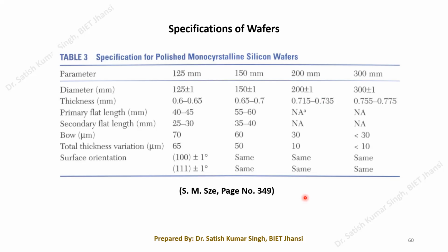So what we need is a very ultra pure wafer. We need to clean the wafers repeatedly so that the wafer is not contaminated by any kind of contamination, whether it is coming from the mechanical operations, the chemical operations, or the environment. Whatever the reason, whatever the source, this contaminant should be removed. So basically we need to understand what the sources of the contaminants are, and how these contaminants will be removed.